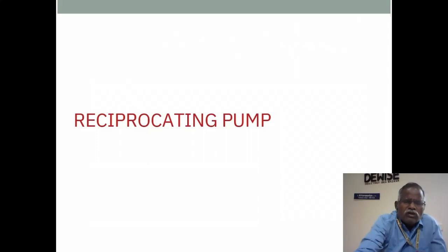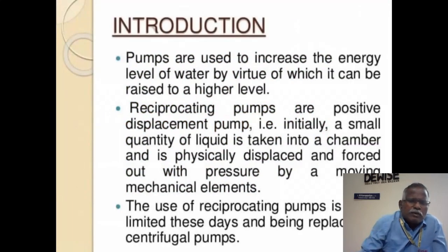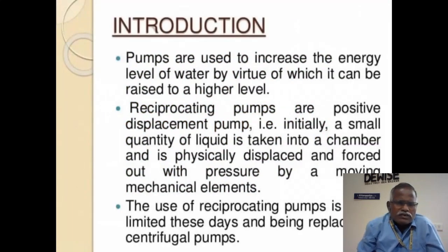Reciprocating pump. Now we go to the reciprocating pump. These pumps are used where there is variation in the energy levels of water. The reciprocating pump is a positive displacement pump. A small quantity of liquid is taken into a chamber and physically displaced by force.